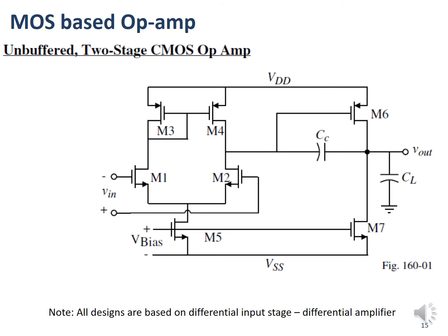So it's a very basic similarity between these 2 types of circuits, and all of them really are based on what's called a differential input stage, where I feed the signal into 2 different transistors that are connected, if you like, in 2 parallel lines, and that then controls the current flowing down each line, and then the relative effect of those is going to control the signal that comes out.